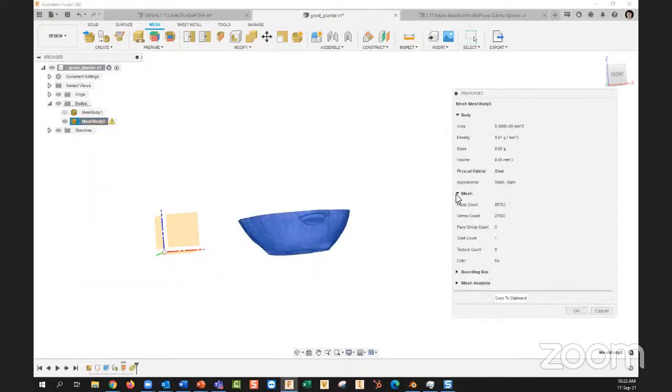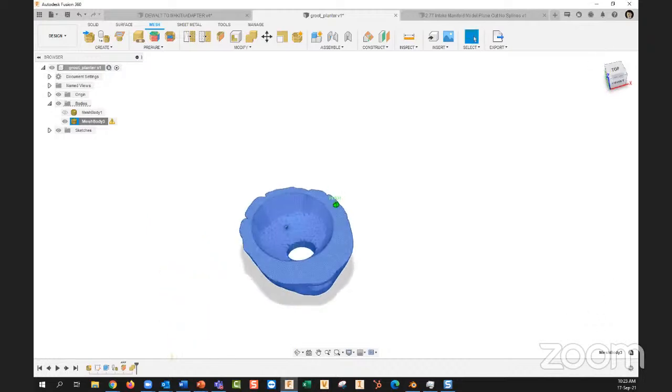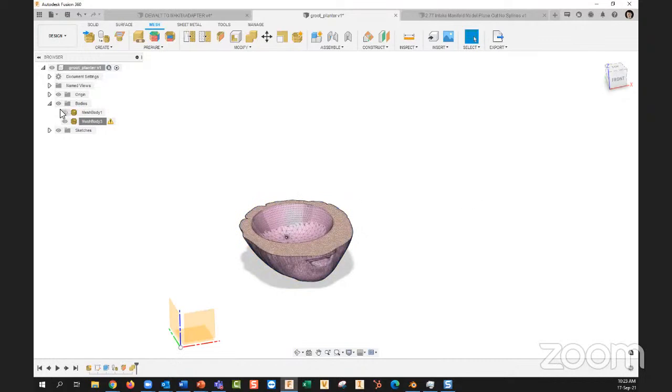Now it is 55,000. As a rule of thumb, and this is just from experience, at 100,000 and more you're going to have a harder time with it. Again, depending on your hardware, your machine, and how much you want to wait, at 100,000 or more, that's when you start to be more cautious when doing a conversion or a combine cut operation.